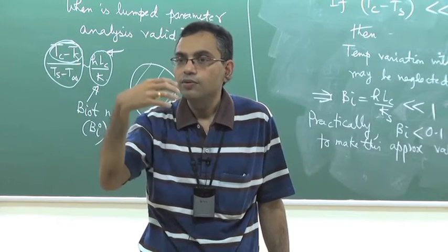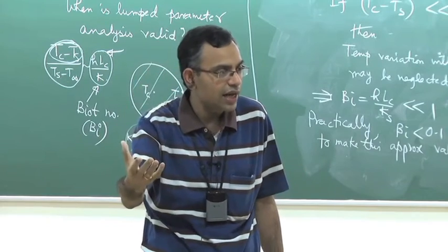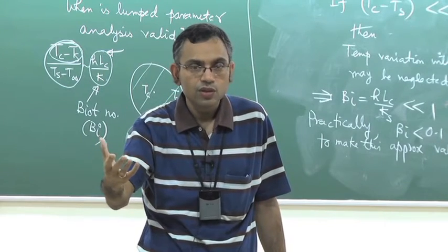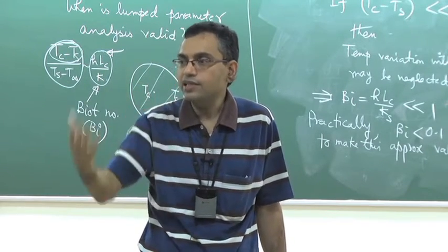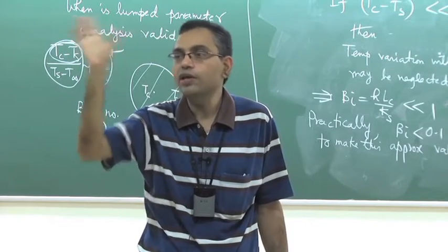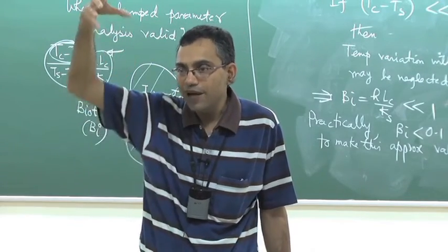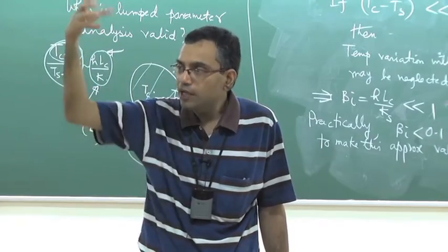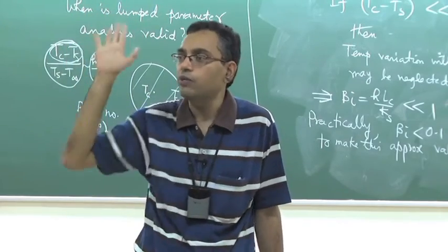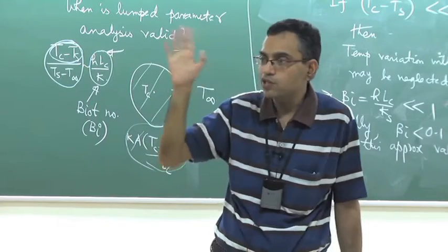That is the requirement of a riser in a casting problem. So the riser should solidify last, because it must supply the molten material to the mold till the final mold solidifies. So riser must solidify last.